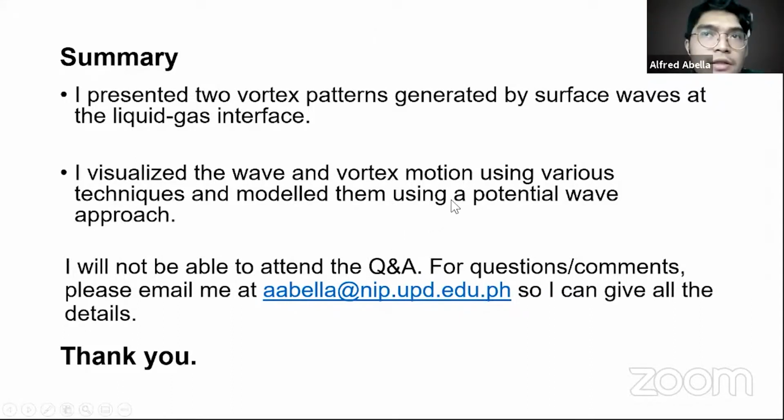It needs to be random because if you use a regular lattice or a regular pattern of dots, then the cross correlation algorithm might get confused. It can associate a particular window to a different window since they look similar, even though the deformation should be just close to that particular window. So you need to have a random dot pattern.